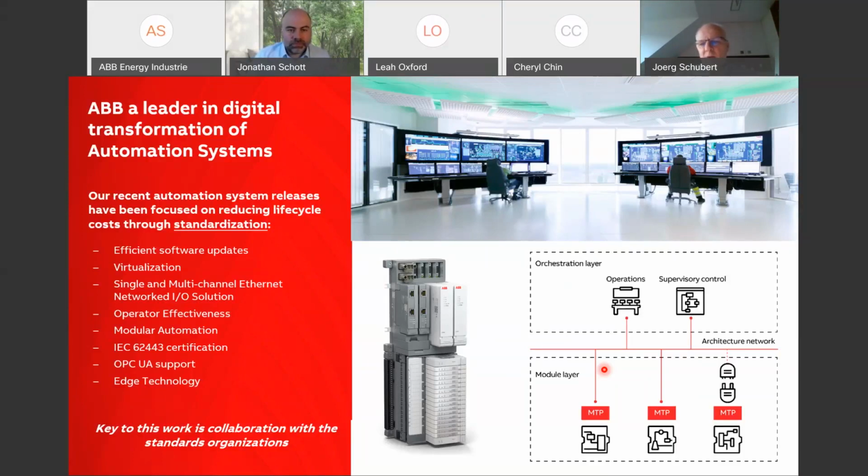We did this in the very beginning by utilizing Fieldbus Foundation technology with high-speed Ethernet. We have introduced electrical integration based on 61850 Ethernet communication, or Profinet, or Ethernet IP. And we have now also connected our system I/O, regardless of whether multi or single channel, to Ethernet, so that we have a network-centric I/O solution that helps us to distribute the I/O points in the system as needed.